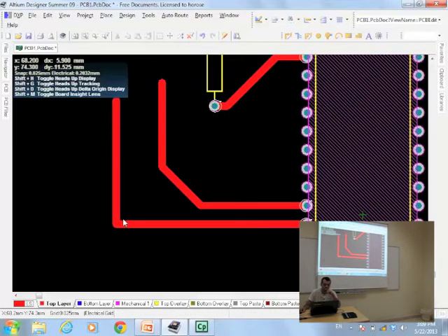The other problem is, you remember in physics that charges concentrate on the pointy places always. So avoid them. And pointy things are very good for radiation. So when you have higher frequency, more than 50 kilohertz, 15 kilohertz, they start radiating. So avoid them. Avoid loops on your PCBs. A signal goes the whole way and goes back to the same place, avoid that.